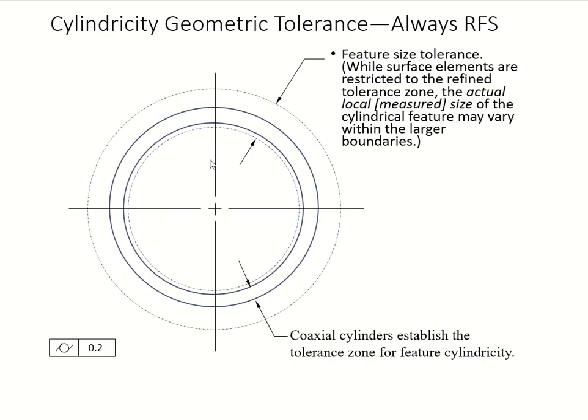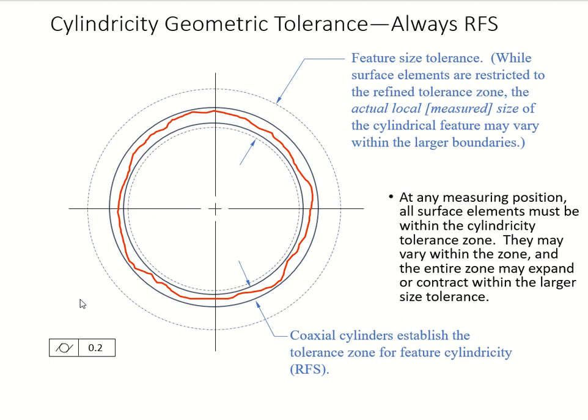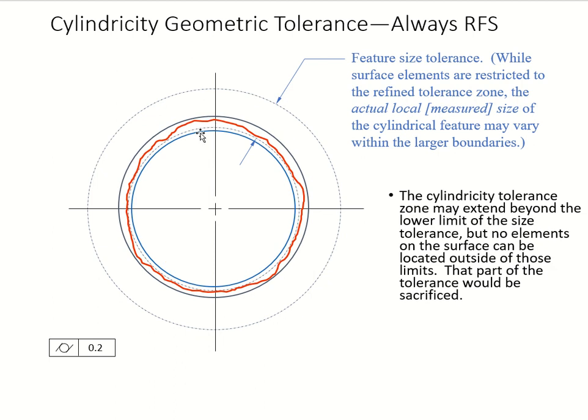All right, so then we can see it a little bit bigger. Here, this is your tolerance zone, and this is your size limit. Your tolerance zone is 0.2, it's set here, and here is our form, which is your true, physical cylinder outside. It's now inside of this tolerance zone, see? Now I'm going to go closer to the lower limit, okay, see that?